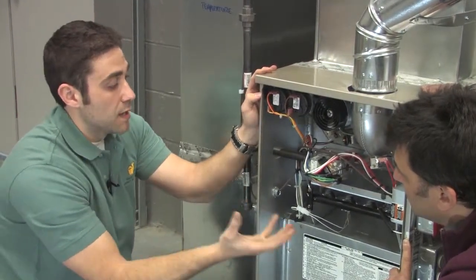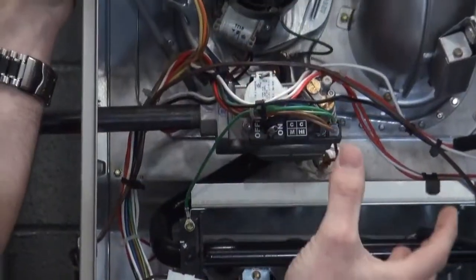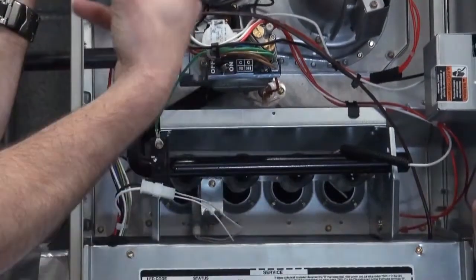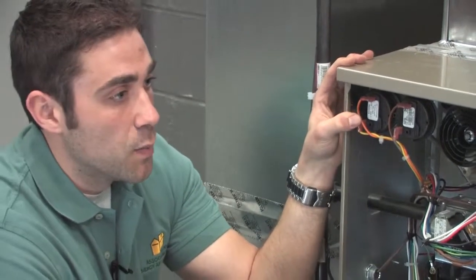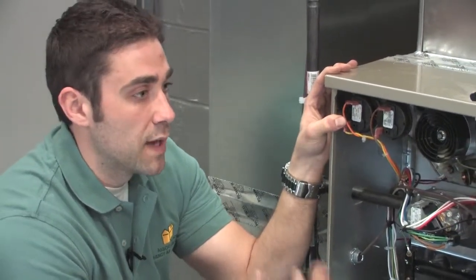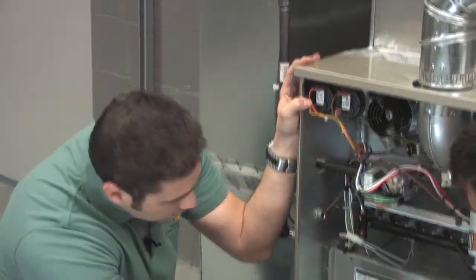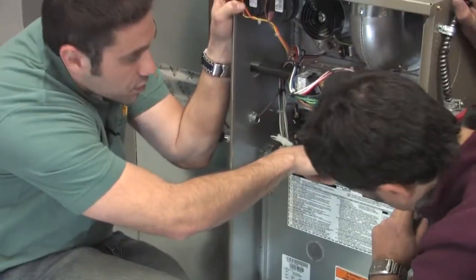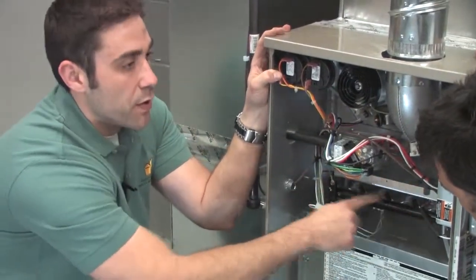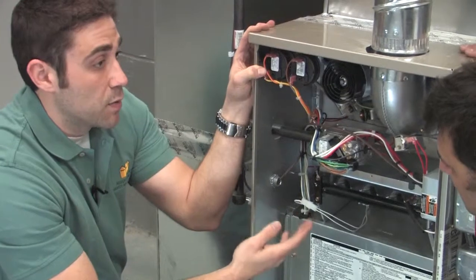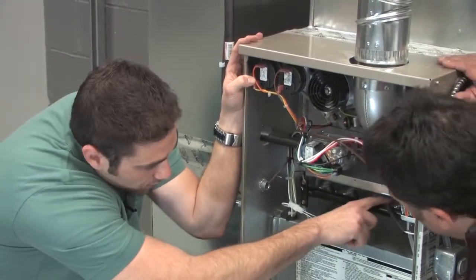Then the system will start to turn on the hot surface igniter. With different ignition systems right now, to ignite our air to fuel mixture, we have a hot surface igniter. So we don't have a pilot, we don't have a spark igniter, we have something that's not going to waste fuel. We won't have that pilot burning gas 24/7. This comes on only when it's needed. So this little igniter right in the back here turns on, and then the gas valve will allow the full flow of gas to come in through these burners and light all the burners up. Now, being that we don't have a pilot, we need to prove that we have a flame. So on the last burner, we have this little flame sensing rod.